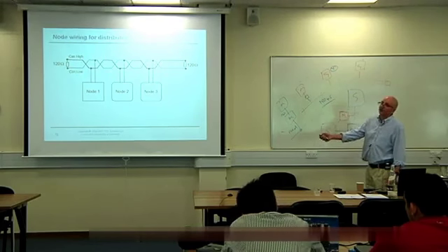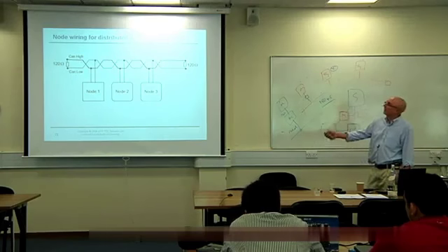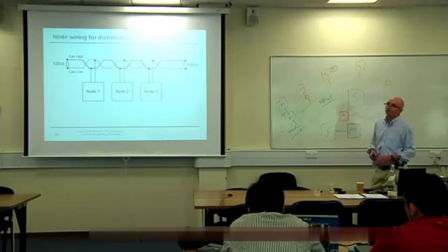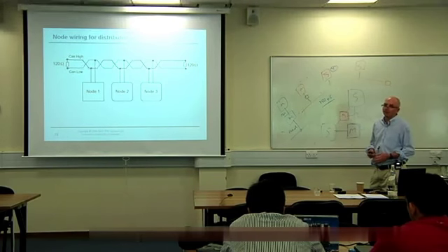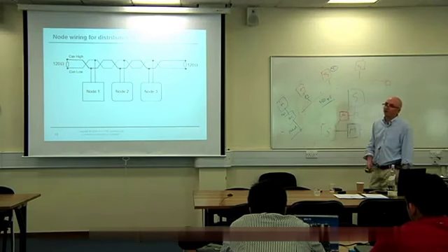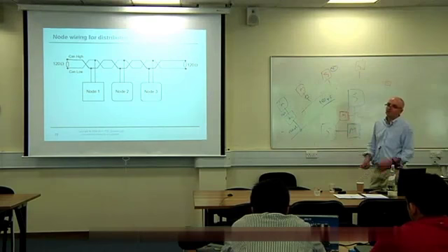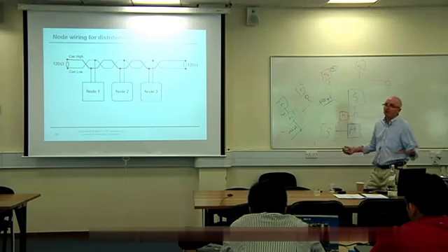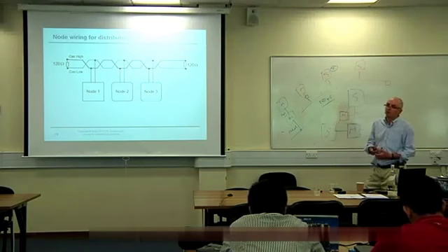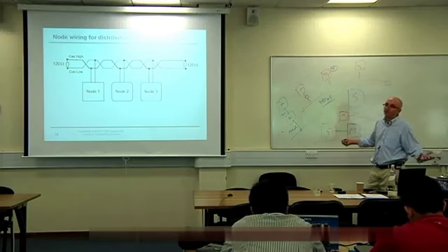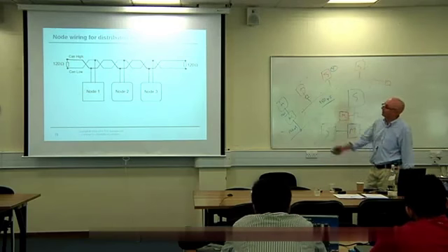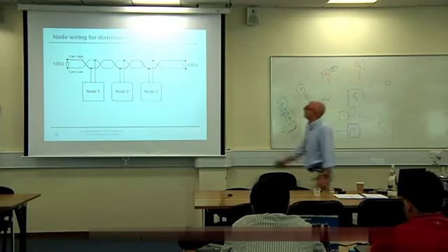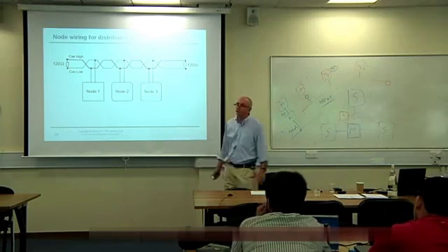It's argued, and sometimes on these networks you can take out one of the cables and it will still work. People argue sometimes this makes it redundant. I think that's absolute rubbish. As soon as you've taken out one of the cables, it's no longer got differential signaling. It's highly sensitive to any levels of electromagnetic interference. That car should be stopped, that plane should be on the ground. It's not redundant, it just happens to be a faintly beneficial side effect, but it's not reliable in those circumstances. If you're going to make it reliable, you probably need two buses.